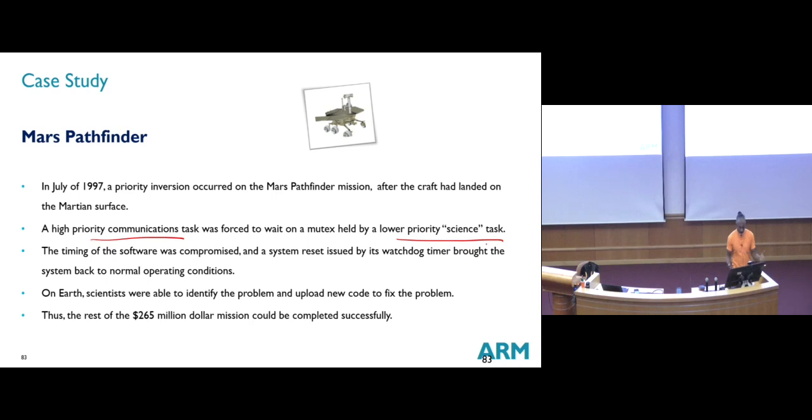And then there was some sort of priority inversion problem, where a low priority task was hogging the system, preventing a high priority task from running. Then a watchdog timer triggered to allow the system back to its normal operating conditions. So what is a watchdog timer?